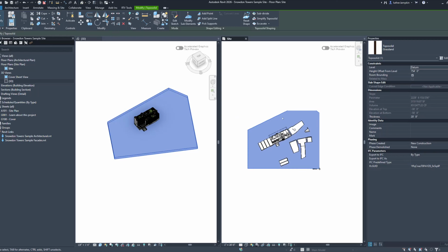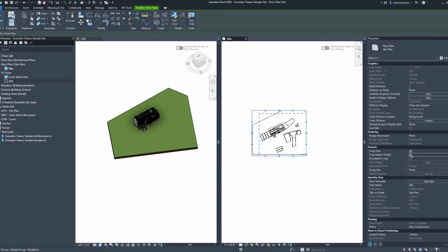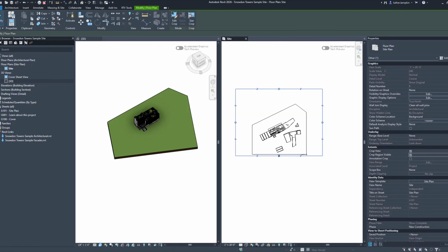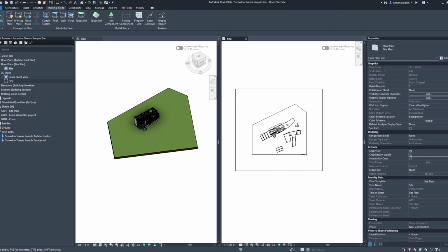And if you ever get this box where it's showing that you cut off a little bit, it is, so what you want to do is just make sure you go over here and do your visible crop setting, just to make sure that you have your crop. It's right here. And so that you can stretch everything else out like you need, so that way you're not cut off on your floor plan. So now I'm just stretching everything out, and then I'll turn this thing off. All right. And so it's super important that we guys are just keeping the visibility of what we're looking at perfectly. So now I'm gonna just uncheck that box again.